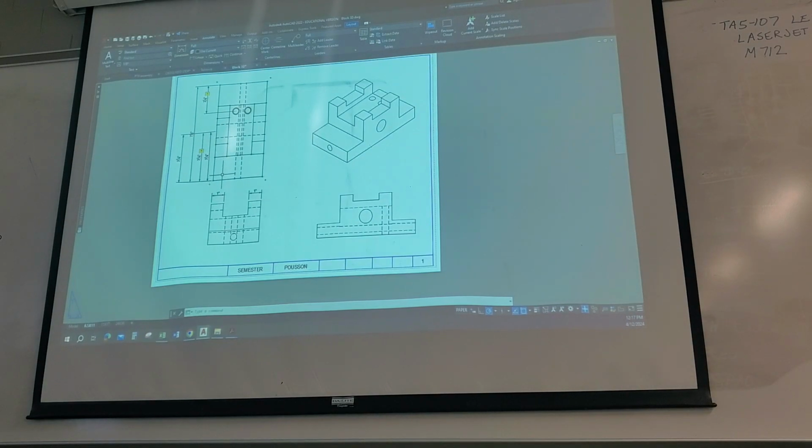The downside to it is that if I go through and modify that part, the dimension right there is not going to be locked to that endpoint of that object. So I may have to come back and fix that dimension later on. Whereas these other dimensions are locked to that endpoint. So if I move that endpoint, those dimensions will automatically adjust with it. Six of one, half a dozen of the other, but if you have to go back and modify something, you'll be happy that those dimensions are locked to the object, not to the point in space, the node.